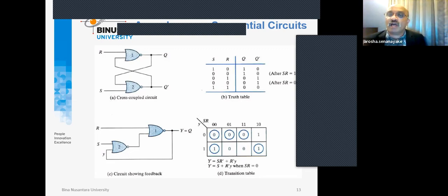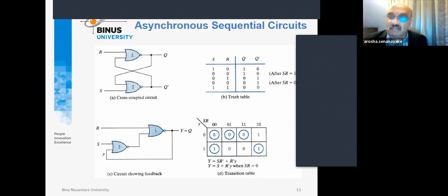Because we are resetting the circuit. Reset means reset is pushed, and then for set, whatever the values do not imply anything. On the other hand, in case of set, as far as set is pressed, we should have the Q change, because now the state is changed. So therefore Q has to be changed. That's how you can see this truth table has been made.